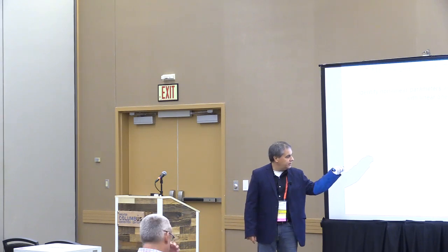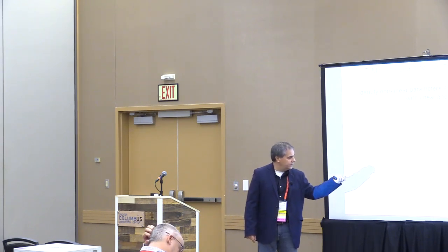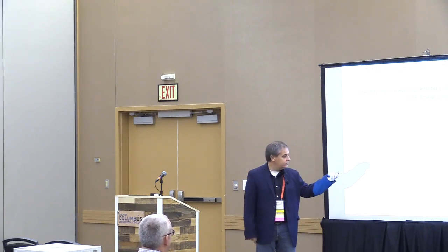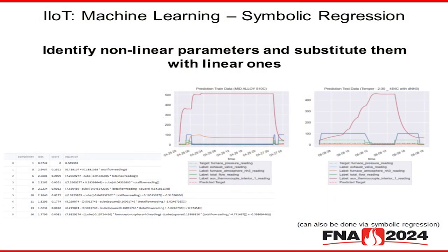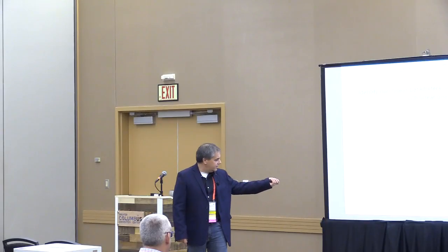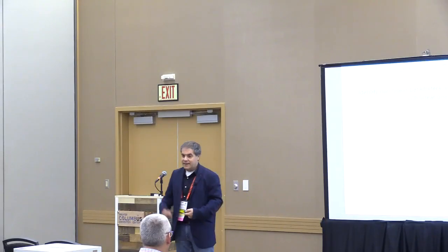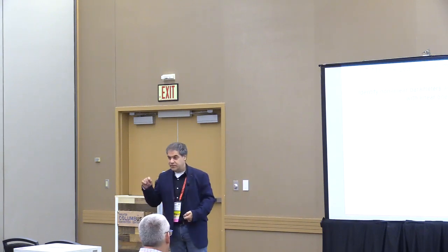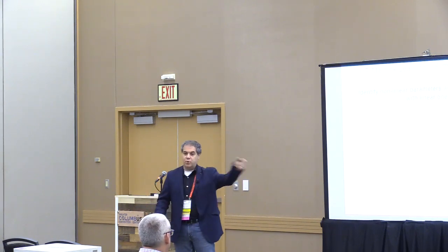Green here is furnace pressure, and predicted is dotted red, according to exhaust valve reading, furnace atmosphere ammonia, total flow, and thermocouple interior 1. The model, at about level 4 complexity, calculated that those are the variables most involved in pressure.